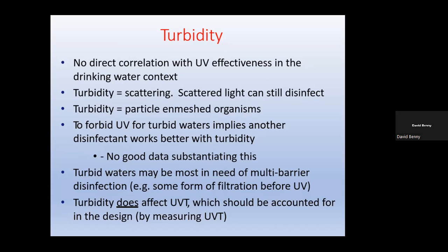Somebody asked me recently, well, how can UV be used in a situation where you have a lagoon and it's functioning properly? So I did some checks, asked people in the industry outside of Trinidad and Tobago, and they said that if you employ microfilters, then UV becomes much more effective.